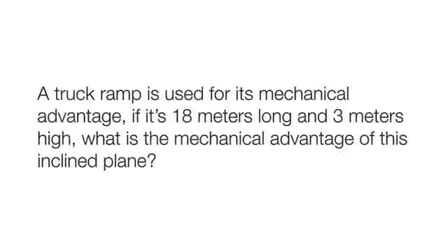Let's try one more practice problem. A truck ramp is used for its mechanical advantage. If it's 18 meters long and 3 meters high, what is the mechanical advantage of this inclined plane? The answer is 6. 18 divided by 3 is 6. I hope that helps.